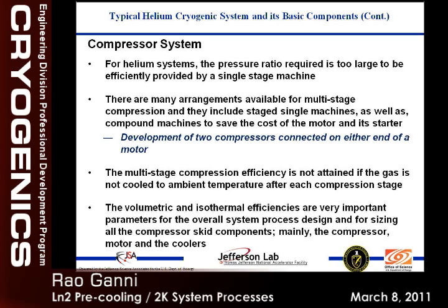The multi-stage compression is not attained if the gas is not cooled. Say, like my car, what they do is they have multi-stage compression. They compress in the first stage, but they inject that back into the second stage, but they do not cool it back. If you don't get rid of the entropy generated at each stage, you won't take all the advantage going to the second stage as good as you could have.